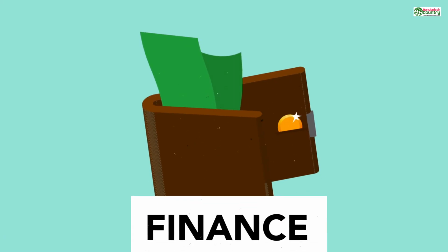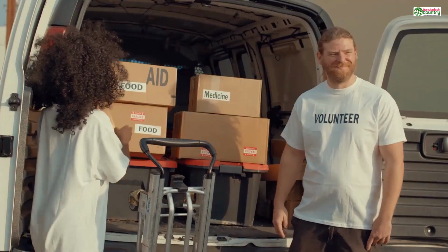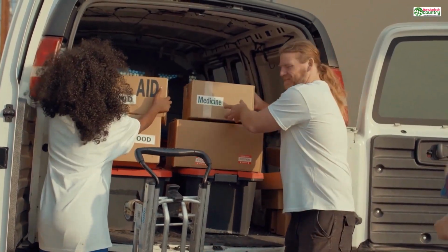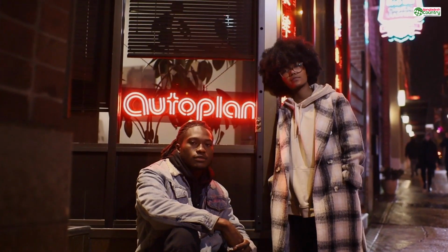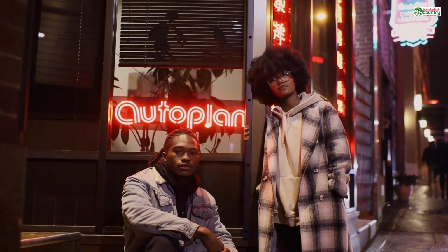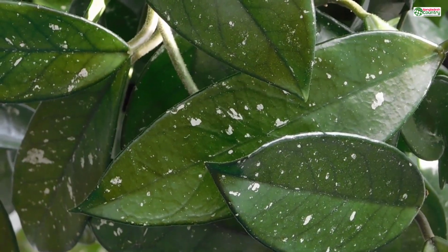So we've hollowed our model to save cost. We've added escape holes to prevent a disaster. We've chosen a smart wall thickness to balance strength and price. We're already ahead of 90% of beginners. But we can take it one step further. What if you have a large model where even a thick wall might not be strong enough? What if you need the lightness of a hollow part but the rigidity of a solid one?